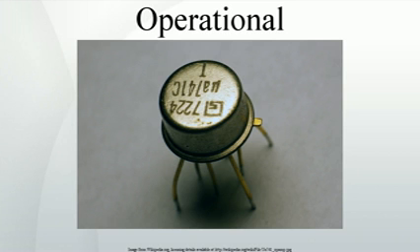The op-amp is one type of differential amplifier. Other types of differential amplifier include the fully differential amplifier, similar to the op-amp, but with two outputs; the instrumentation amplifier, usually built from three op-amps; the isolation amplifier, similar to the instrumentation amplifier, but with tolerance to common-mode voltages that would destroy an ordinary op-amp; and the negative feedback amplifier, usually built from one or more op-amps and a resistive feedback network.